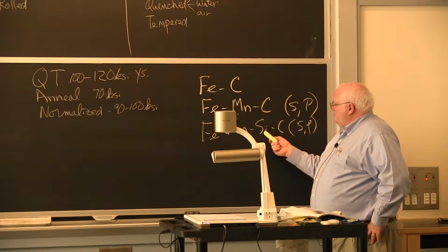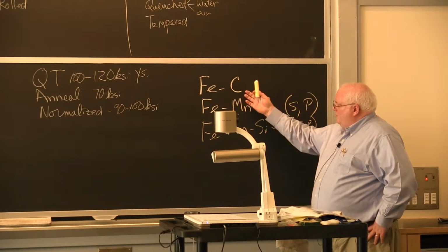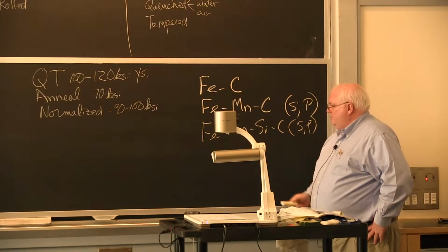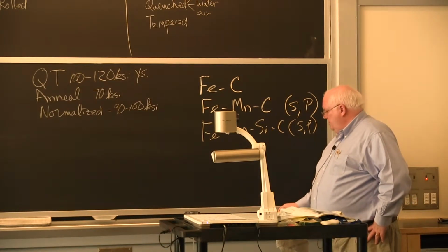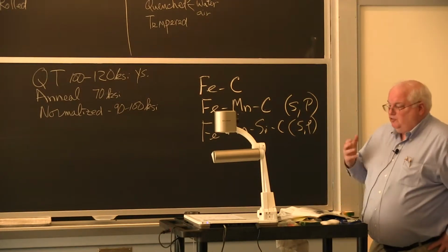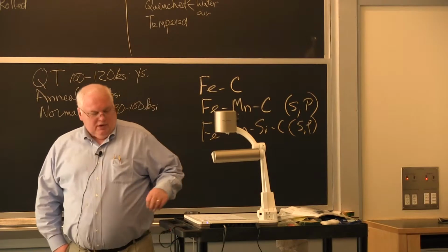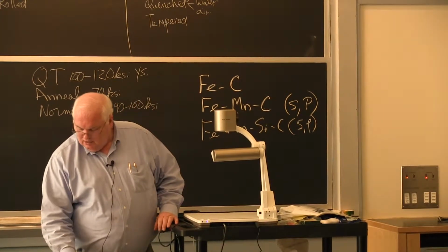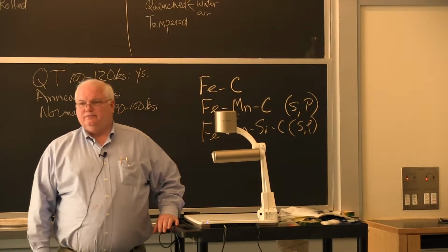The silicon is sometimes put in to get the oxygen out of the steel. Once you burn the carbon out, you're burning it out with oxygen, which means you're throwing a lot of oxygen into the steel. If you don't get a lot of that oxygen out, you'll get bad properties, so you throw some silicon in to tie up, actually make little quartz particles, SiO2 inclusions in the steel, which are not terribly harmful. So that's some general steel making technology. Anybody have any questions on that?